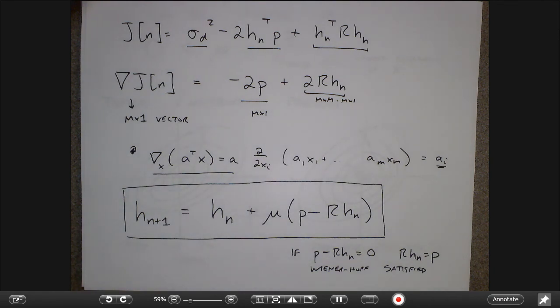It also is a big matrix equation. And so you could imagine that you could adaptively adjust your filter taps in the same way as I do this. Instead of using the backslash operator in MATLAB like you did in that homework, you could apply this steepest descent algorithm to find the best filter taps numerically. A different cost function would be the Chebyshev cost function. There, I have a very different cost function that says I want to minimize the maximum ripple or deviation from the amplitude response. That is a much different cost function than something like this.